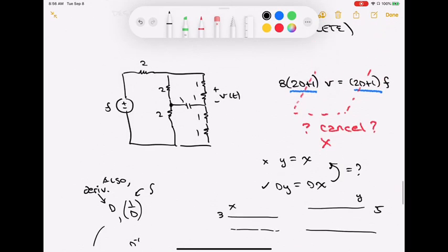How about if I did an external view of this circuit? So back to this one. We did an internal view. That internal view gave us a first order differential equation. Now if I do an external view on this, I'm going to make an assumption in here. I'm going to assume that the capacitor is initially discharged. Okay, you build the circuit up, you go grab a capacitor from the shelf in the shop, and sure enough, it shouldn't have a voltage on there.